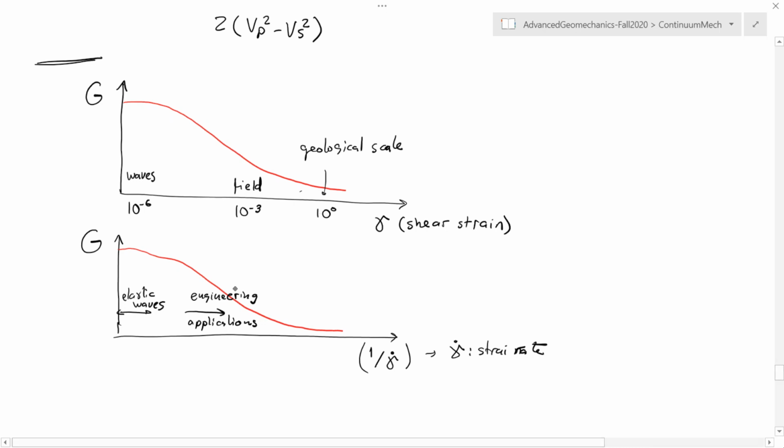And usually what is done in these mechanical earth models is to simply apply an empirical conversion in the lack of some other more precise data that links the static Young modulus to the dynamic Young modulus, to a conversion factor from dynamic to static, which is a function of the dynamic modulus. All right.